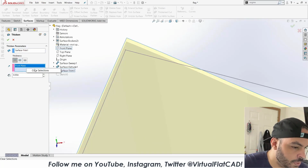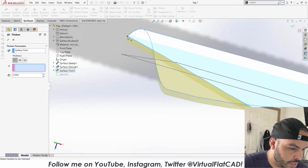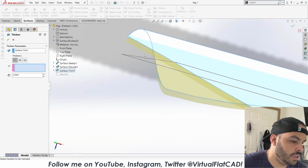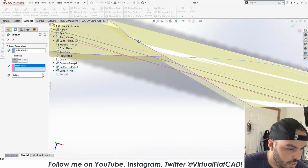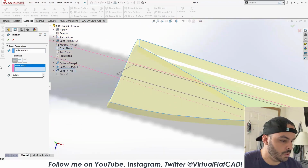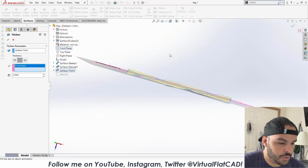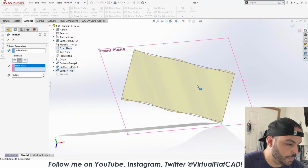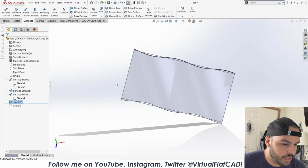Because if I don't put a specific direction, you see it alters the direction. You see it's actually jutting out a little bit because it wants to make a 90-degree angle, and the line might not actually cut all the way through. So by putting that front direction, it ensures it comes straight to that trimming line, and it will match up just perfectly. There we go.